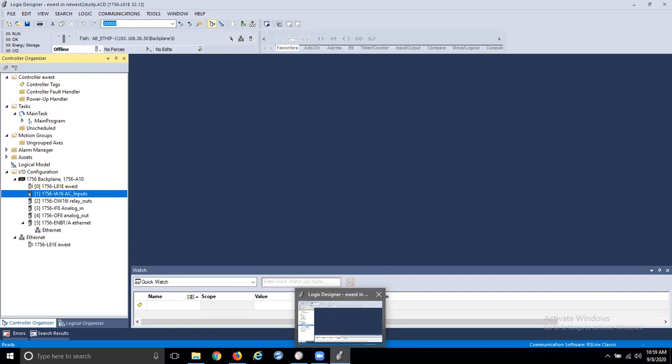So in the Click software, you had the address picker. You could go in and put in nicknames and everything else, and your memory is basically organized. You knew what you could use and what you couldn't use. In Allen Bradley, it's what we call tag based. And so the tags are created as you need them, and the different tag types are available as you need them.